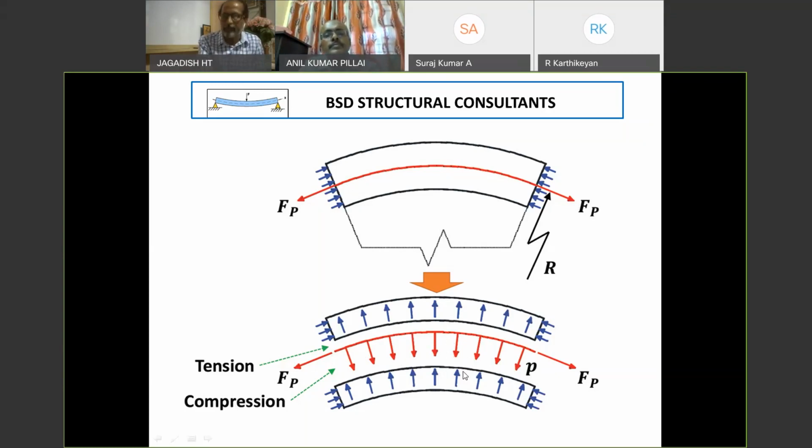But because it's covered with concrete all around, it will apply pressure on the concrete. So the concrete below this will experience pushing, and there will be a split happening at this line, between above and below. We call this radial tension. When we talk about split tensile strength, this is where we are concerned that in this portion, the split tensile strength of concrete should be adequate. So this radial tension of the cable pulling the concrete down caused delamination along this joint.